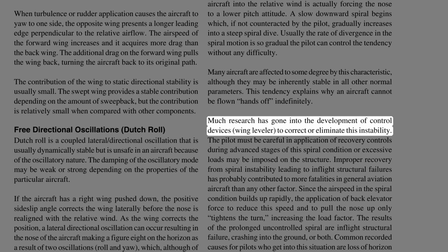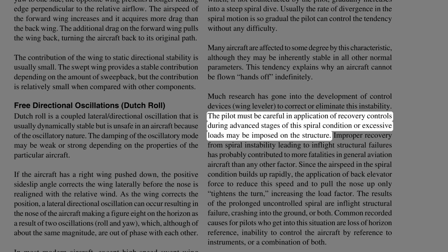Much research has gone into the development of control devices, wing levelers, to correct or eliminate this instability. The pilot must be careful in application of recovery controls during advanced stages of this spiral condition or excessive loads may be imposed on the structure.